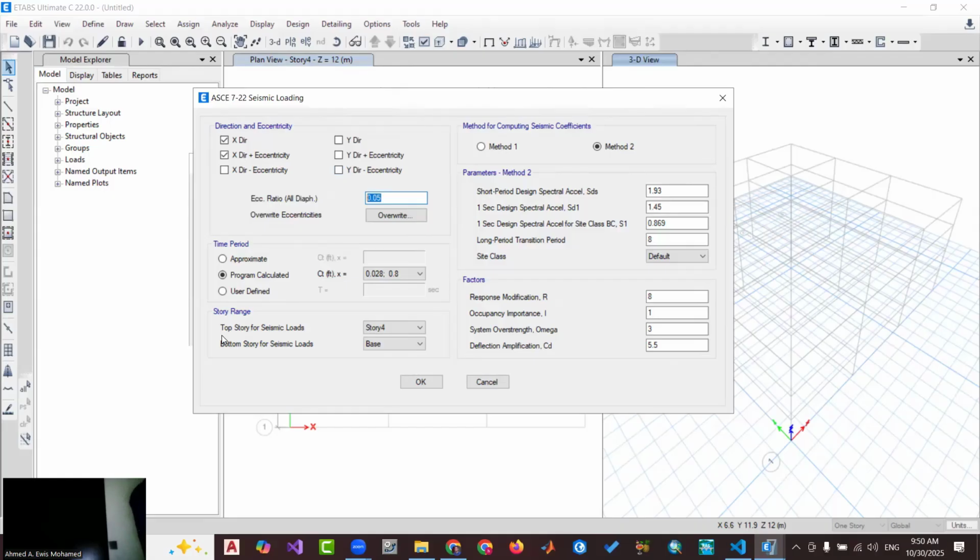So for this one, we can say it's in the middle, because we have the same weight anywhere. And for the rigidity, our center of rigidity depends on the distribution of shear walls and columns, the members which can resist the earthquake. For this also, it will be in the middle. So center of mass and center of rigidity will be the same.